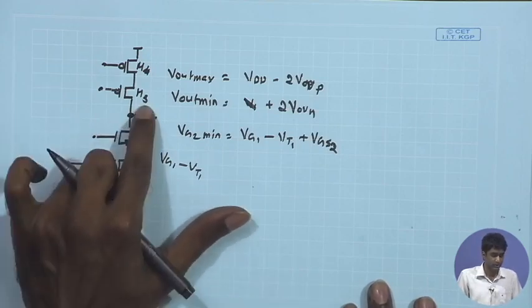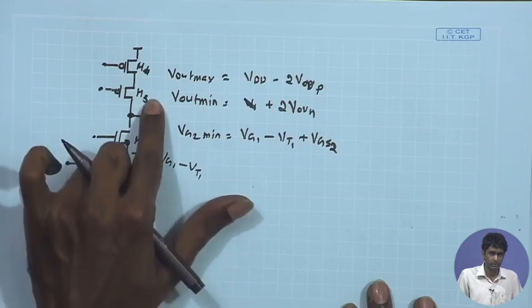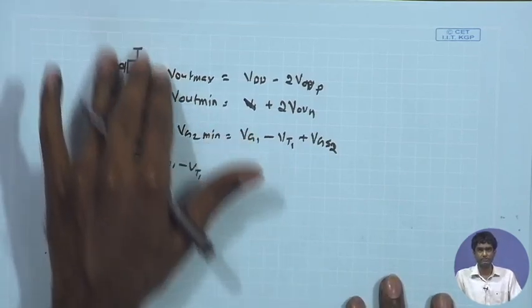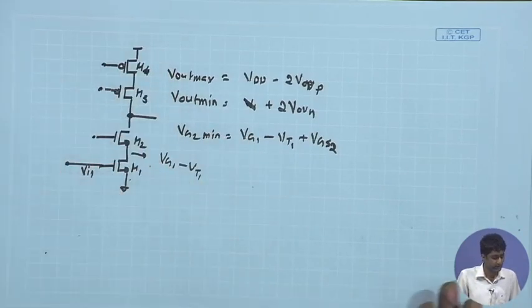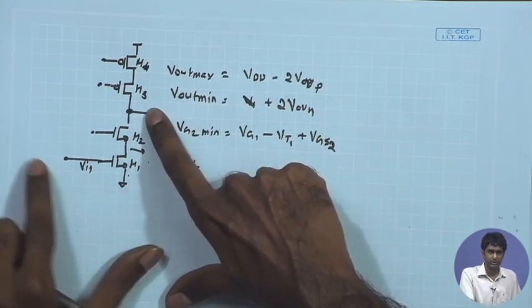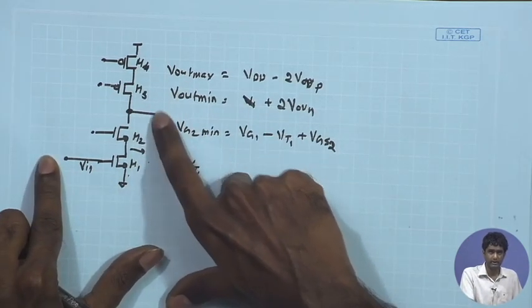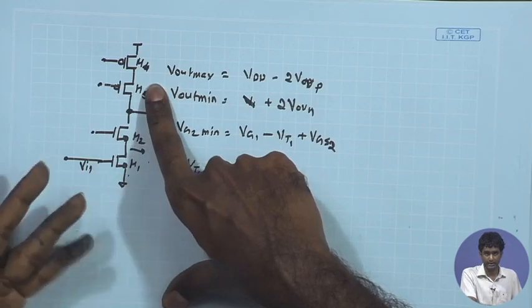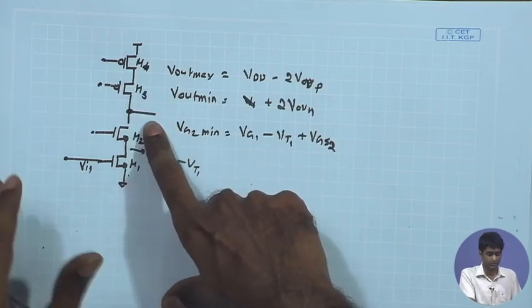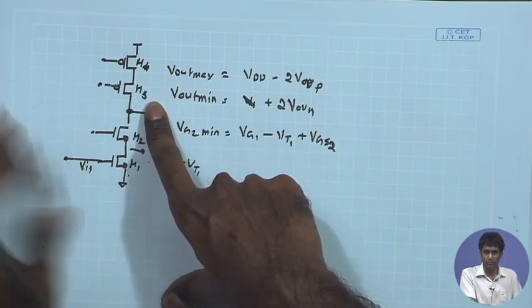Now, the signal swing over here of course depends upon the overall signal swing over here in the open loop case. So, if I am just using this amplifier in open loop, I do not worry about signal swing, because the signal swing over here will be dictated by the maximum signal swing over here divided by the gain. Maximum signal swing is maybe 1 volt for a 1.8 volt supply.